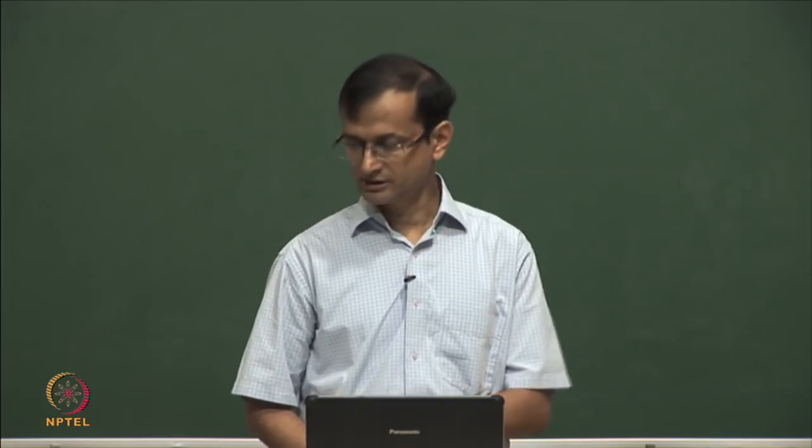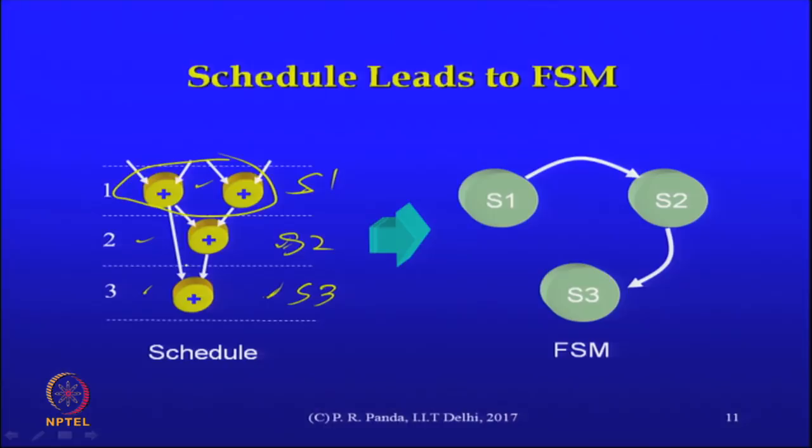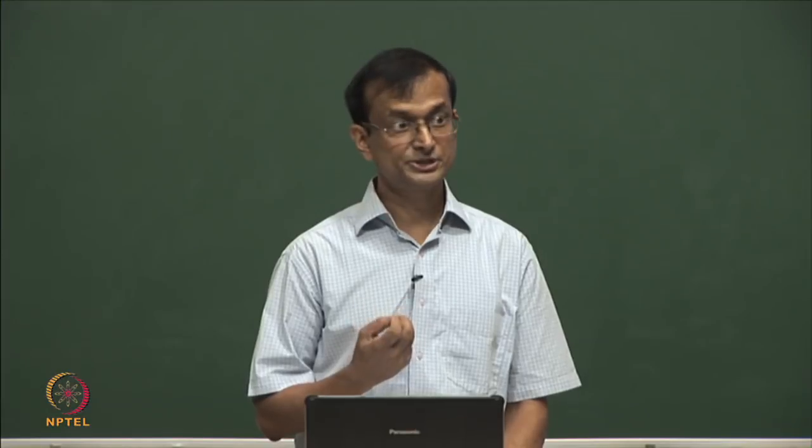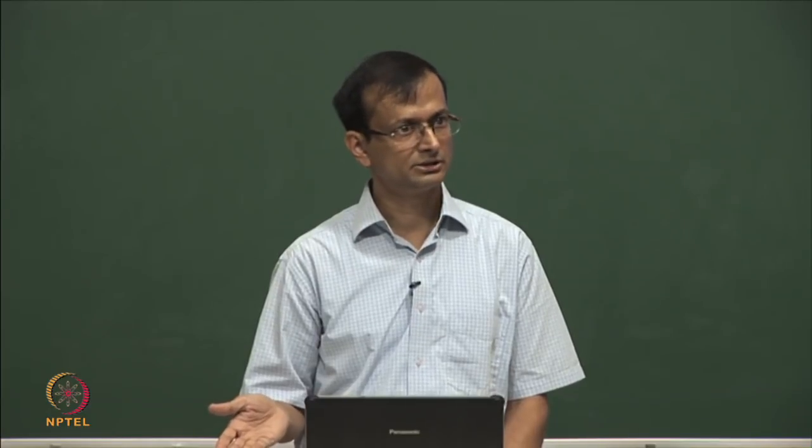Of course, for this schedule to work, it is essential that the adder delay be less than the clock period, otherwise this does not work. So, both of those pieces of information, what is the adder delay and what is the clock period, must have been known to the scheduler. Otherwise, you would generate an illegal schedule.